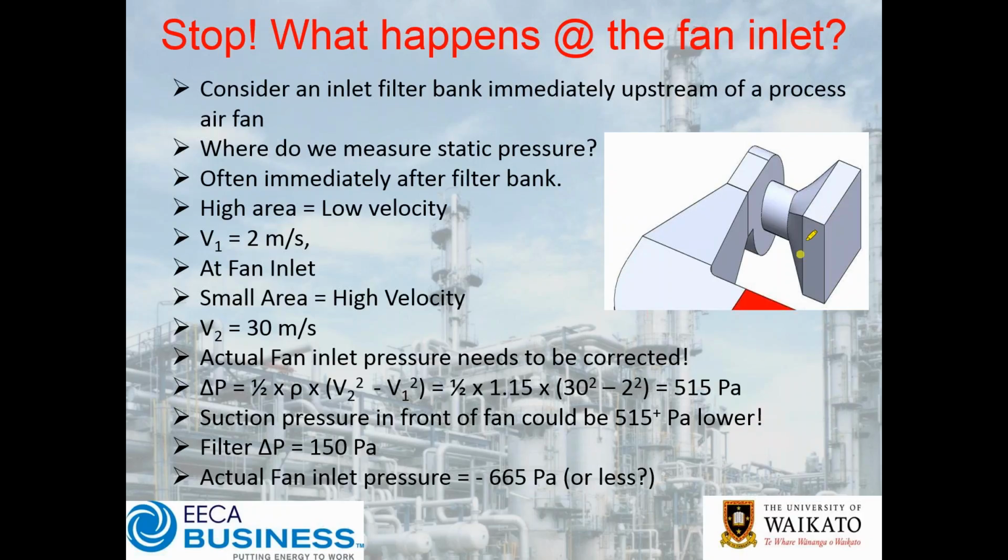Now of course what happens as we reduce down our area and we look at the pressure right here at the fan intake, what you've got to be careful of is that your measurement here isn't actually the suction pressure of the fan. The suction pressure of the fan is actually what we've got here. So the question is, what happens between here and there?